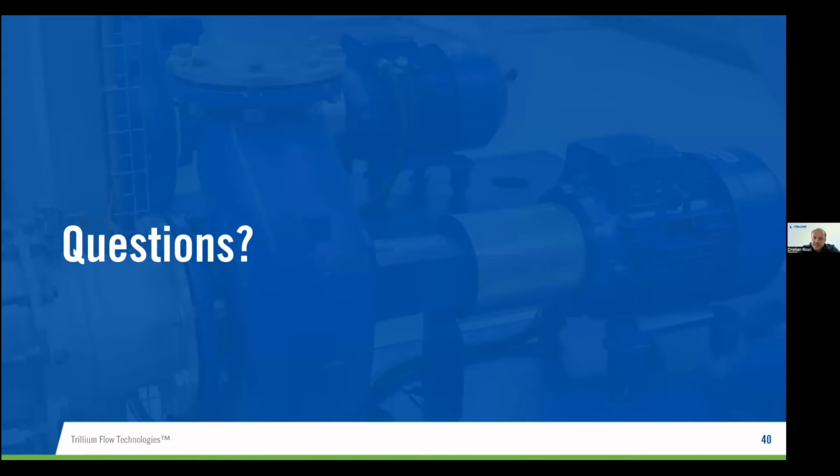Okay, in general, steam turbine-driven pumps are equipped with a governor that is designed to regulate the speed of the turbine and therefore the speed of the unit. It happens sometimes that during the years, after operation, the steam turbine can be no longer available, and the client requires moving the driving system from steam turbine to electric motor.